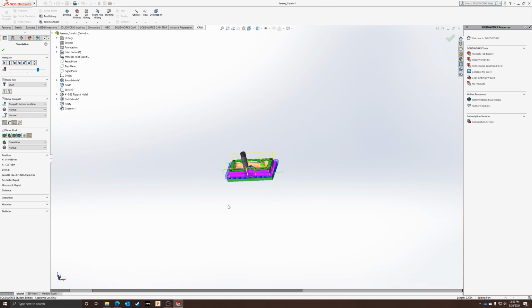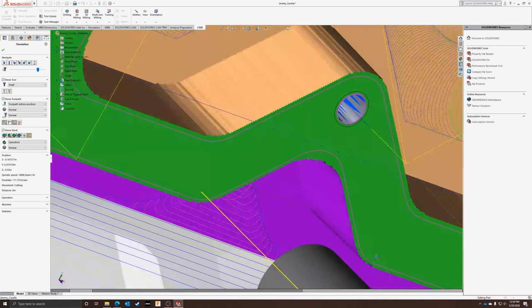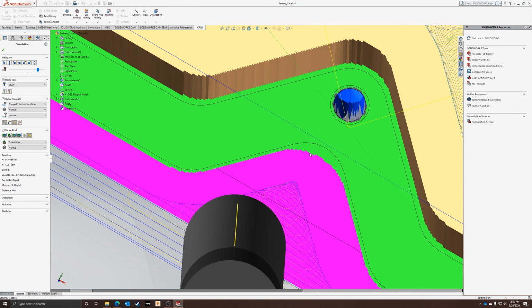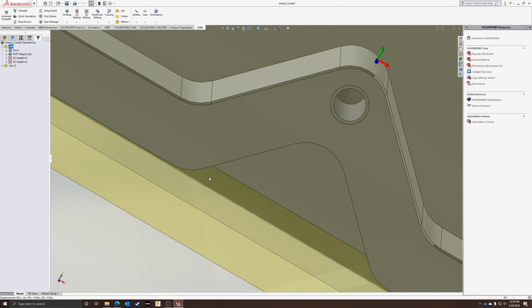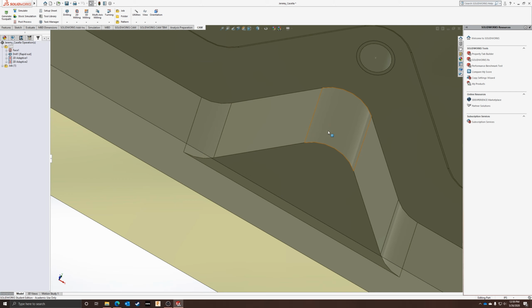And once again, we run into that issue here. You'll see there's a lot of material left over. That's more than 0.02 inches. That'll snap my tool. What do I do? Well, here's the solution. We got to look at our part and think about it in context. If I have a 1/2 inch end mill and this is a circle of 0.4 inches, it's not going to fit in that radius, so it's going to get as close as it can.